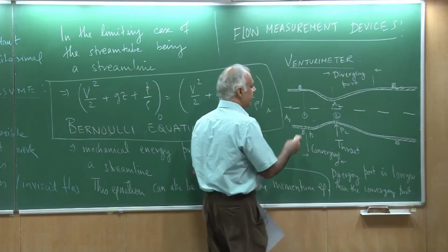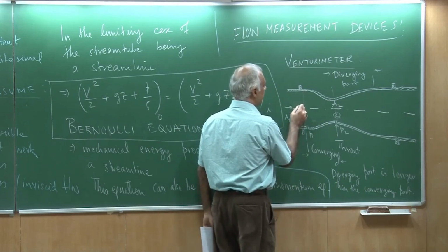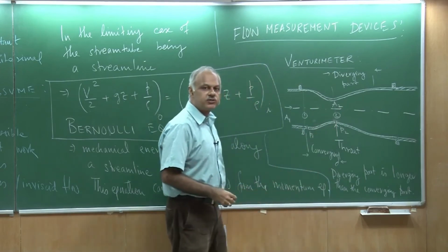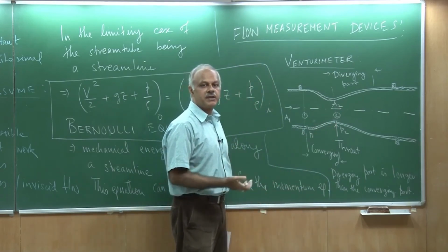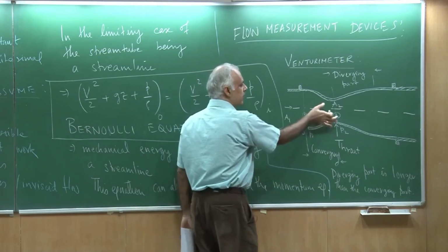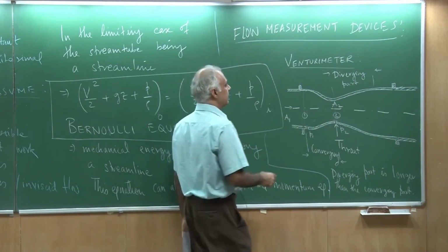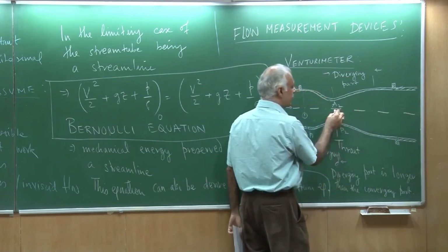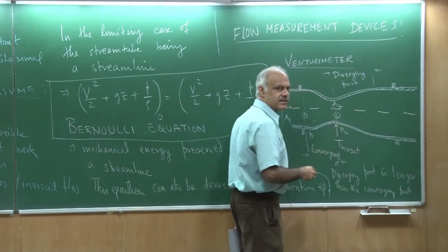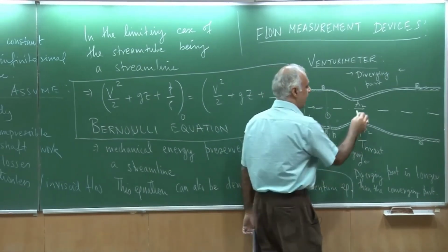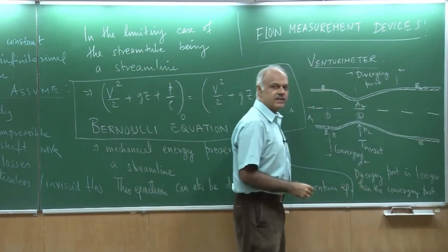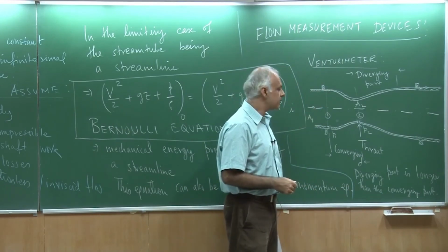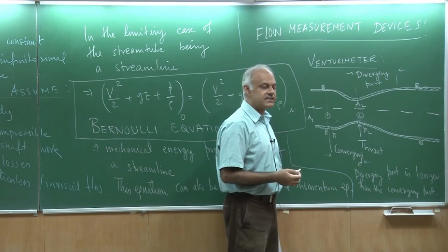What is happening here is I go from a high pressure to low pressure. So in this part, the pressure is reducing and we call it a favorable pressure gradient. The flow is moving towards low pressure. Okay. On the other hand, my pressure recovers here. So I had low pressure here because it's a high speed moving fluid, and then in the divergent section the fluid again retains its old speed. Okay, it becomes slower and then the pressure increases.